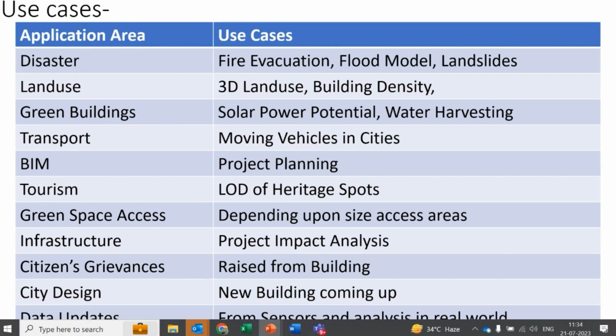We can also analyze the building density. Building density matters because we are talking about compact city development. So building density is one of the inferences that will give you an idea of how I need to plan for increasing the density of that area, increasing the FAR. Now we are also having this TDR based plan. So we can also see how the building density is going to impact that type of development.